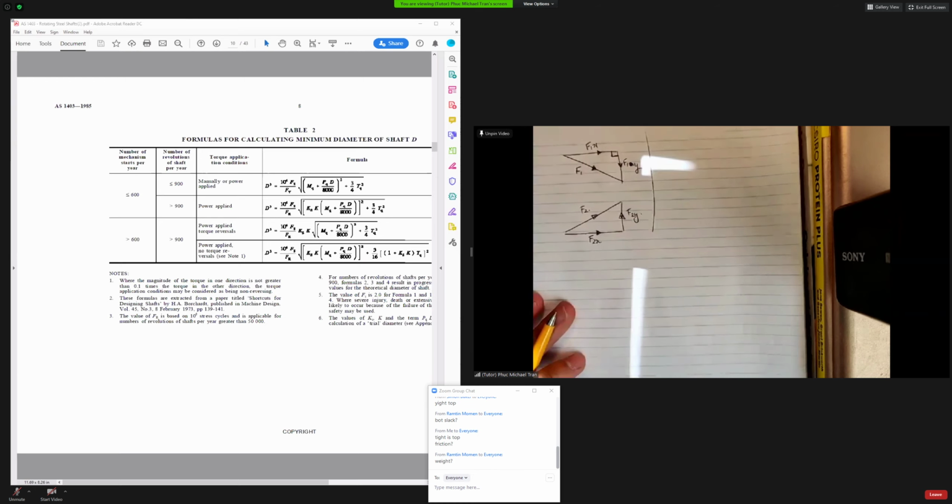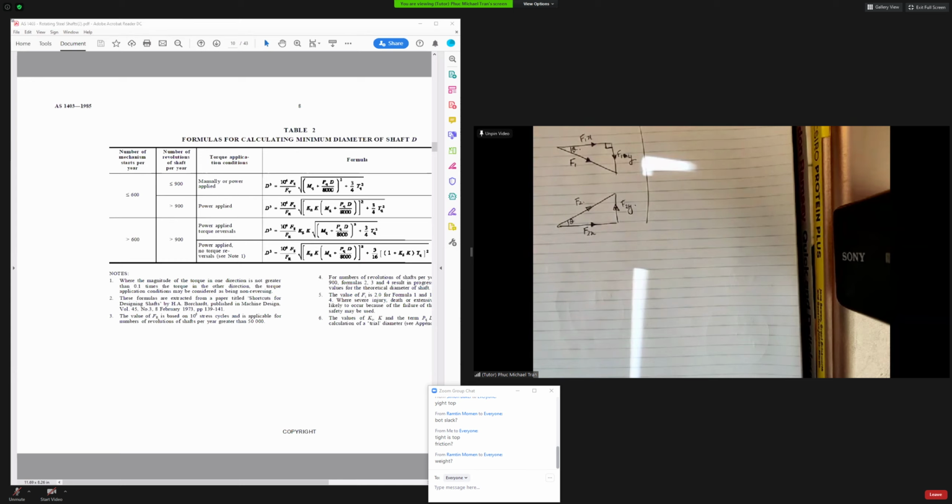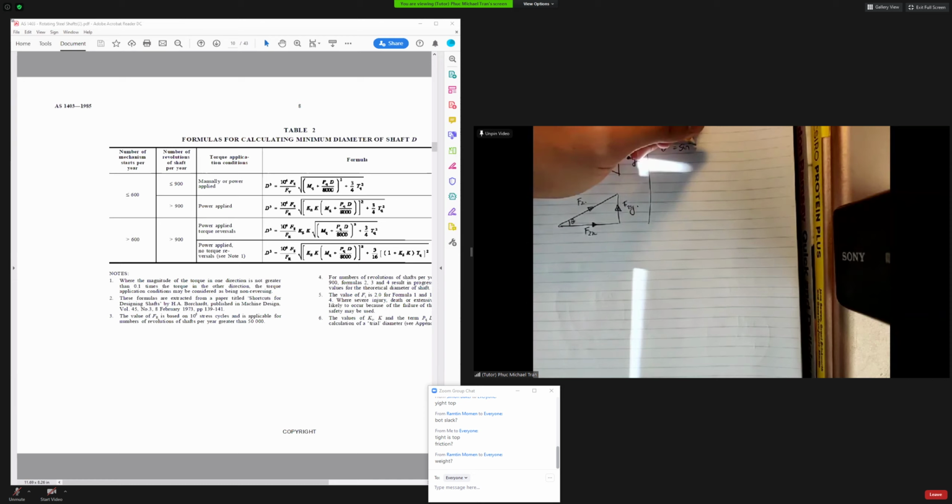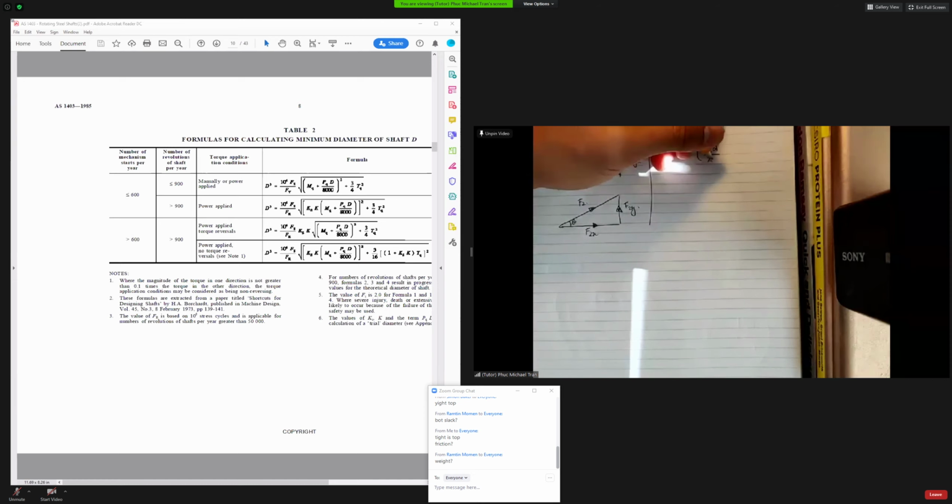So the critical component that we need is this angle, and these are going to be the same unless you have an offset pulley system, which is weird, but don't do that. So it'll be the same as your contact angle, sine^-1 of (D minus d) over 2C.